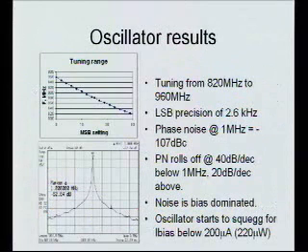Okay, so just some measurement results so you believe it works. This is the measured frequency across just the MSB settings from the lowest to the highest, and you can see it covers about 140. What did I claim? Yeah, about 140 megahertz of range, around 900 megahertz. So it hit my band of interest. It's a little low. That always happens. And it hit my range I wanted.